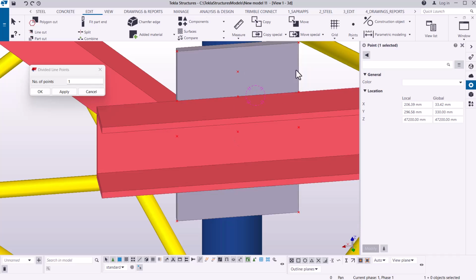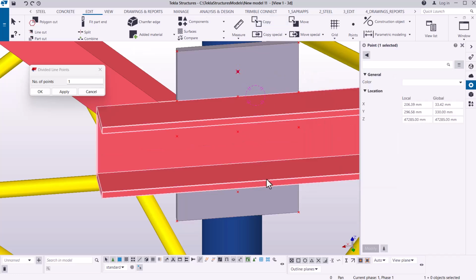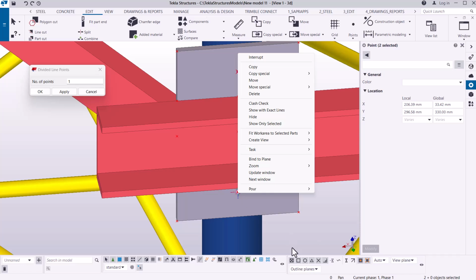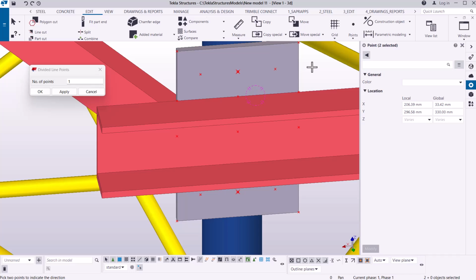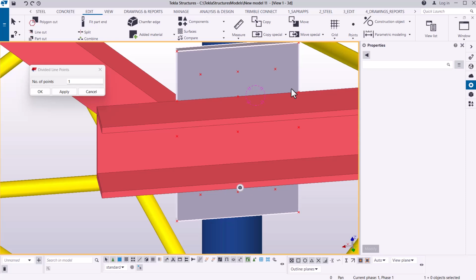I can as well just copy that by using this handle here, and copy that direction, and use these two and copy them in the x direction. So I'll use special copy, and I want to offset this way on the x-axis, both by 48. So I have to prefix the first one, prefix this dimension by 48, and remove that prefix of negative 48, so we have that in place. So this will be the positions of the holes, so we'll leave it as it is.